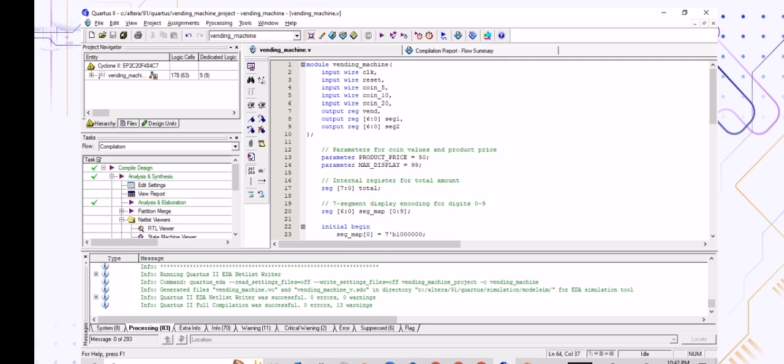First, we define a module, and under this module, we declare the inputs and outputs. First, we declared the CLK, or the clock. It checks the inputs at regular intervals. During these intervals, we can ensure that the operations in the machine are synchronized and it updates properly.